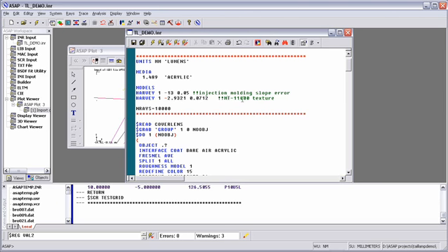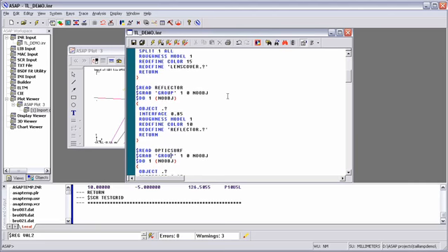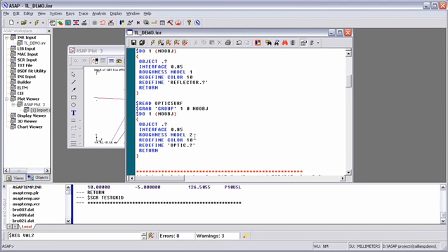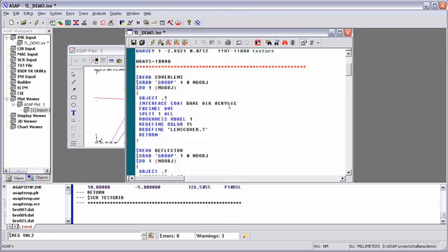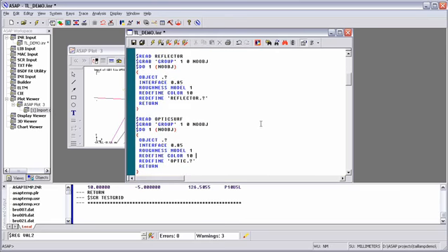The other thing I've got set up in this particular file is a texture. For those of you familiar with injection molded parts, a lot of times they'll put on something called stipple or Mold-Tech finishes. In this case, I've simulated that reflector using that texture. If I wanted to find out what the performance is without that texture, I simply have to change my model back to just the bare molded slope part, and I could rerun my simulation and have that result.